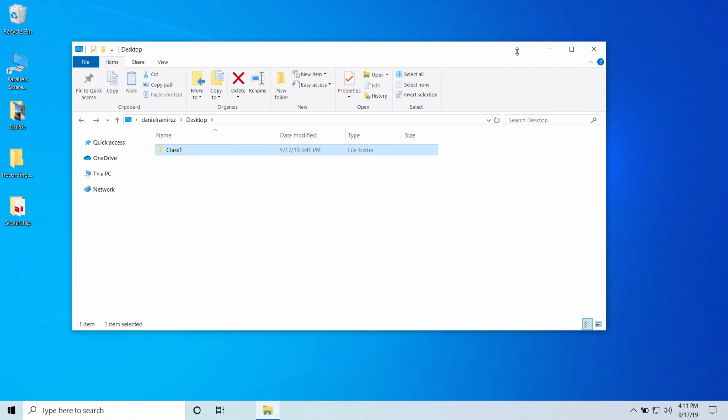This is Windows now, okay? In my experience with Abaqus, you have to be very organized about where your files are. Because if you're doing one or two simulations, it's okay, you don't have to be organized. However, if you are going to run several cases, or you are going to do a convergence analysis of the stresses near the crack, you have to be very organized with your names and where you are storing the files. So on the desktop, I have created a folder called class 1, and that's where all my files are going to be stored, okay?